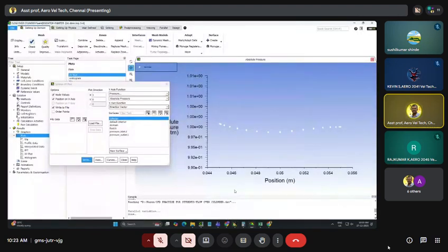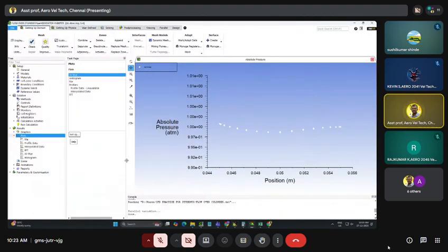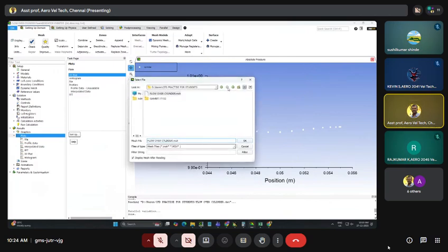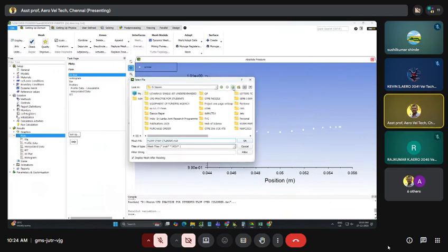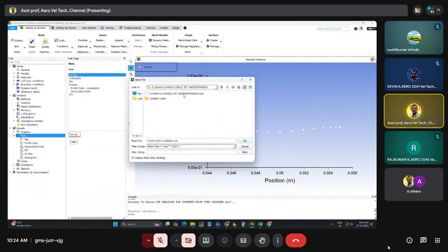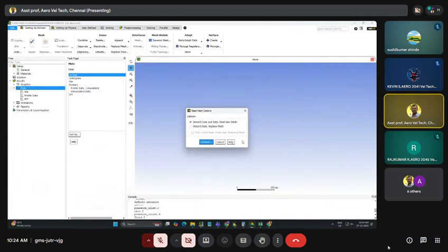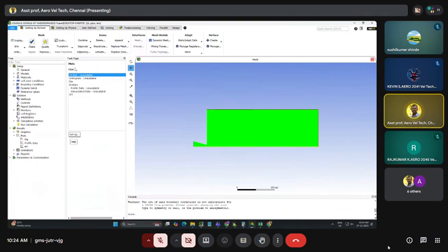Okay. Now in here, you can see I will open Fluent. I'll just file read mesh. So I have already opened something, so you have to discard everything. You continue newly. So, okay, lower Raju single jet underexpanded dot msh. You open this. Okay. So you will get a warning as usual.